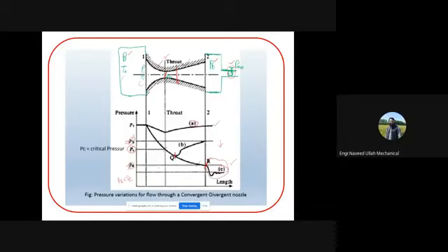Here there is no velocity graph, otherwise we could show that this further pressure drop inside the diverging nozzle causes velocity to increase. Here the velocity will become sonic velocity, right? But after that, since the pressure drops in this diverging section, the velocity further increases and goes beyond this sonic velocity, and that is your supersonic velocity. But after that, let's say after passing this point, it decreases, and at exit you are having less velocity or subsonic velocity. So I should say